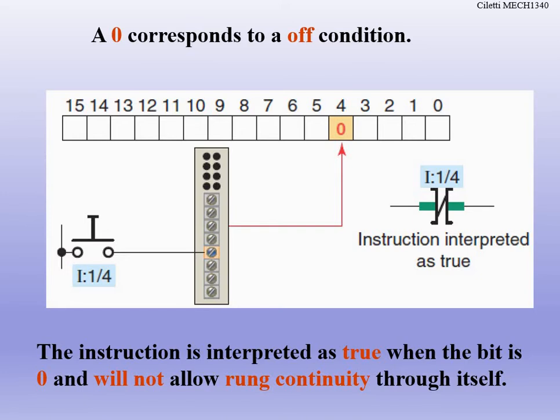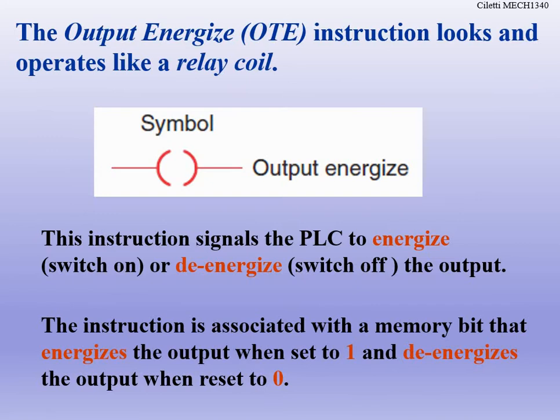So what we're really interpreting, look at this input switch. This input switch here is normally open. Okay? You can just tell by the way the symbol is drawn. But we're using a normally closed contactor. So what's going to happen is when this push button goes down, it's going to flip what's happening here on the contactor.